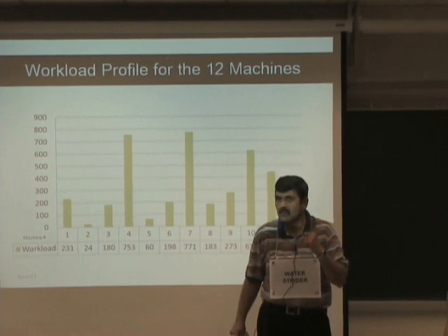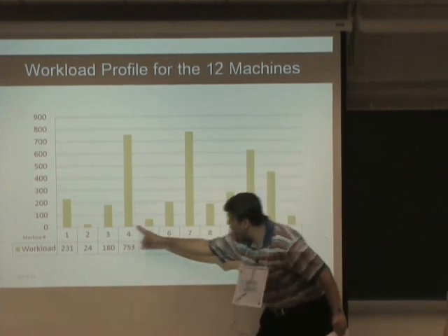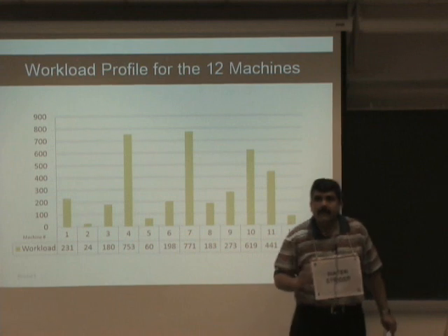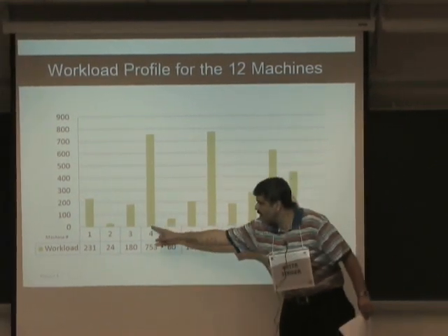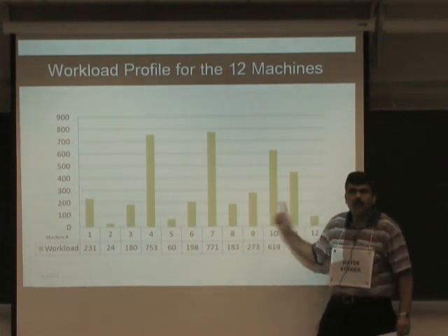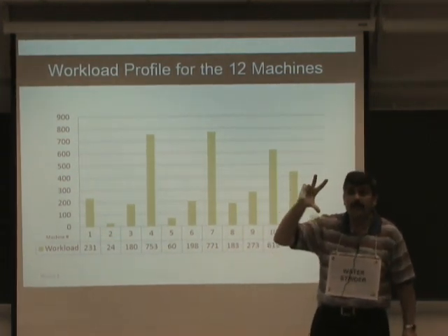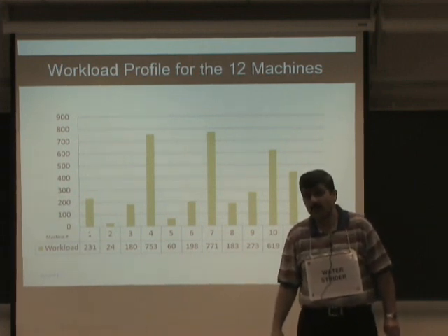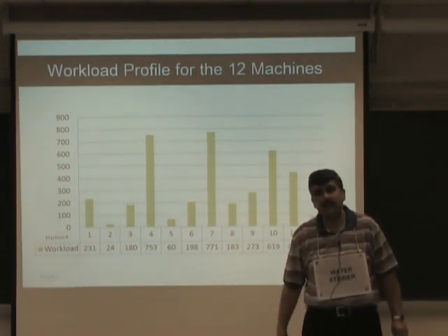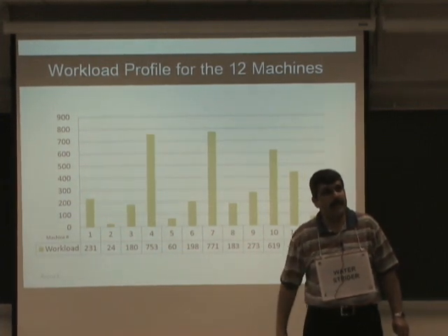Over-processing waste. So when you get such profiles, you go back and ask which products are being processed at these machines. Which of those products have a very high work content compared to the work content of other operations they go through? Then you go through a design for manufacture analysis and an equipment capability analysis.